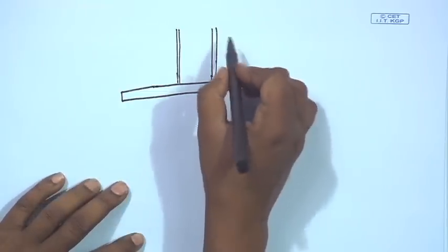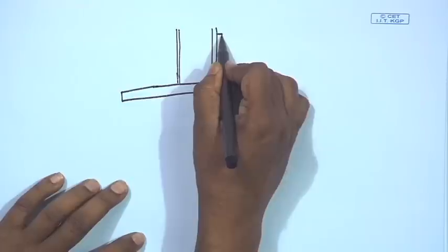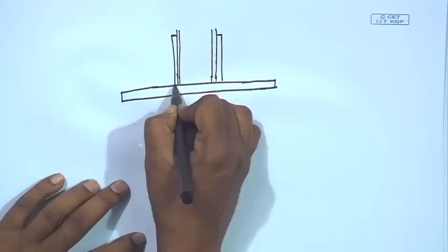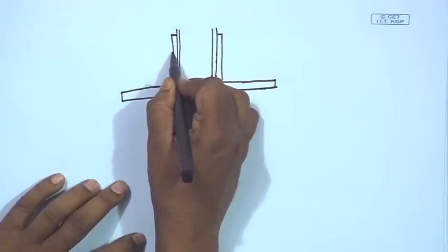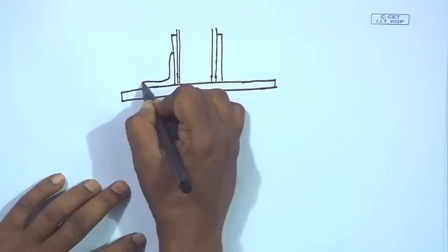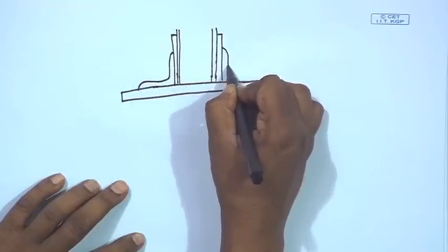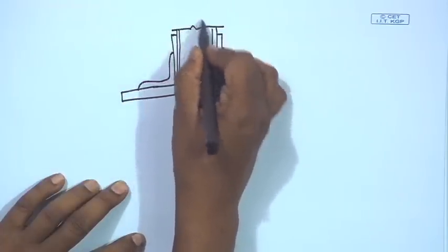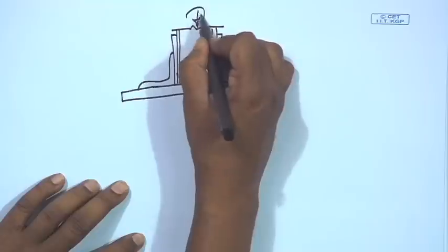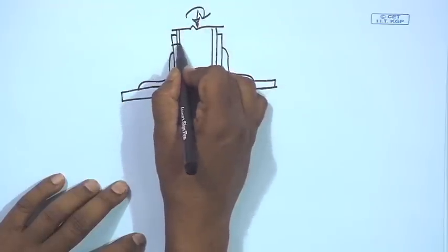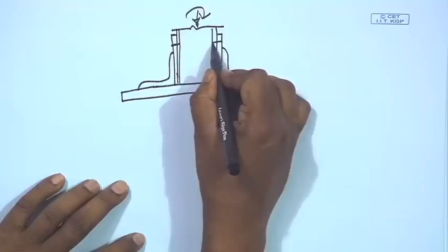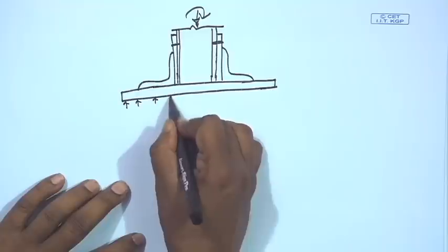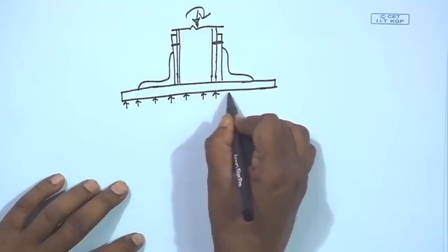Here, we are providing an additional gusset plate on the column, and this gusset plate is again connected with the gusset angle. So, the load coming, whether it is load or moment or both, is transferred to the base plate through the gusset plate and through bearing. Okay. So, in both ways it is transferring the load.